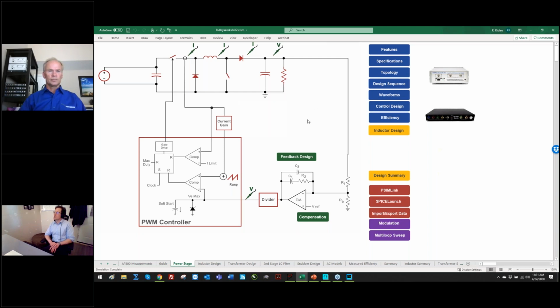So there's another interesting question here, which is I'm using the word unstable in the sense that the output is very underdamped. It takes hundreds or thousands of cycles to damp out, or it starts to oscillate and hit resonance. Those are different, in my words, from a stable circuit, which has a steady state, something that has a repeatable waveform from one cycle to the next.